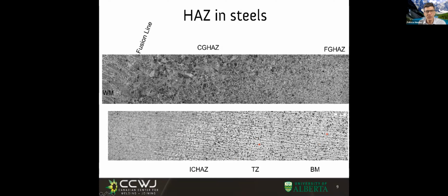But when we get closer, you're gonna see that although this was below the transformation temperature, the heat still had an effect and modified a little bit the look of the perlite. Super interesting. The thing speaks because we see these different morphologies. That means different peak temperatures.